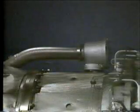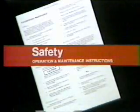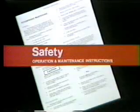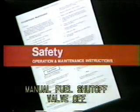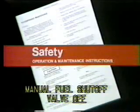Here is your instructor. Job Program 1, Bleed Air Valve Maintenance. Maintenance work on the turbine package or any of its components must not proceed until the supply of fuel gas to the package is locked off at the source, the manual fuel shutoff valve. This valve must be locked off and tagged Danger, Do not operate.